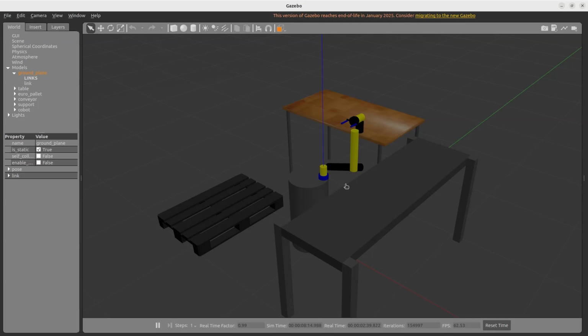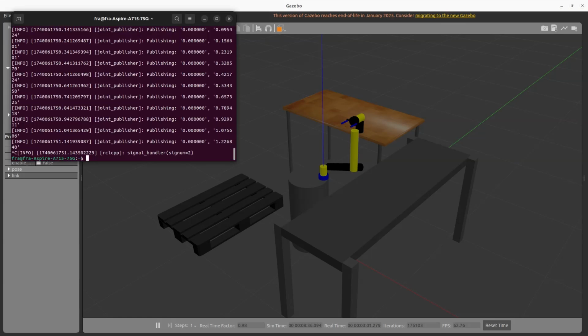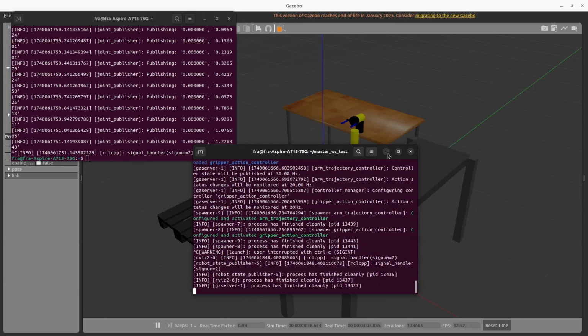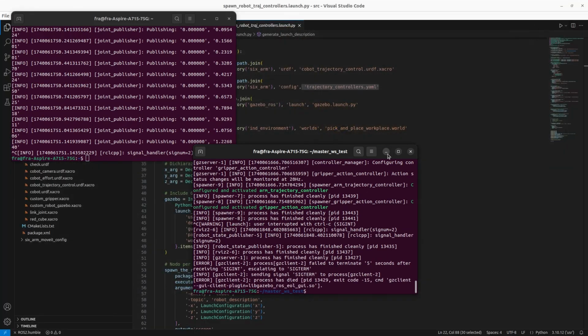Okay, and the best tool, or better, the best framework to do this is MoveIt. And if we run in ROS2, then we have to run MoveIt2, and for doing that, we are going to install MoveIt2 with respect to the ROS2 distribution, and in this case it's going to be Humble. Okay, so let's close everything here, and now let's install MoveIt in binary first.